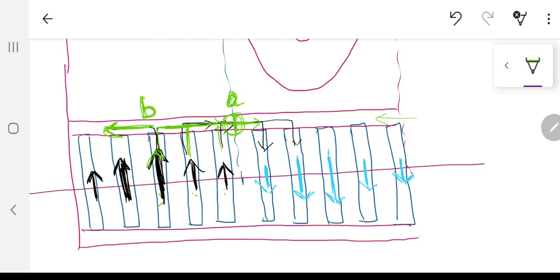Now this is a very important point. Listen to this very carefully. At point A, all the bars, which means bar number 1, bar number 2, and half of this bar, 2.5 bars, are putting the current through this end ring. I am concerned with the end ring current at present. So point A is going to have the currents from 2.5 bars, and at point B the current is still flowing. It's not that the current is not flowing, but at that particular point where the third bar of that north pole is actually there, at that point half of the current is being split, so point B is at 0 current.